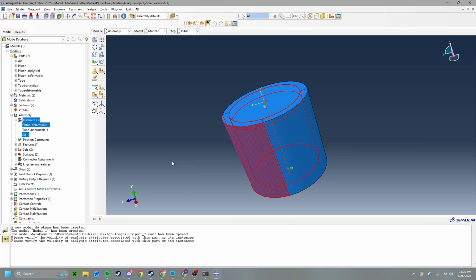The important thing is Eulerian components stay stationary in space. They only model a mass fraction inside them, like the flow in and out. They're doing volumetric analysis with integrals over all the sides of the elements. Kind of somewhat similar to a heat transfer problem where you got heat fluxes, you got mass fluxes through these ones.